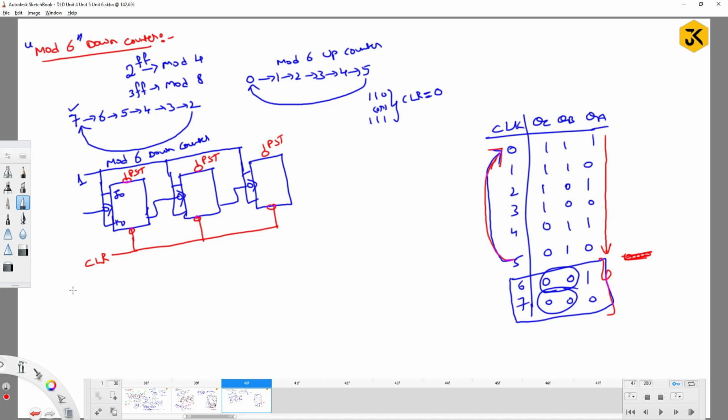If you remember the earlier one, in the active low state, preset, clear and Q states work like this: to get the output as 1, preset should be 0 and clear should be 1. So for that reason, you can make use of this combination.